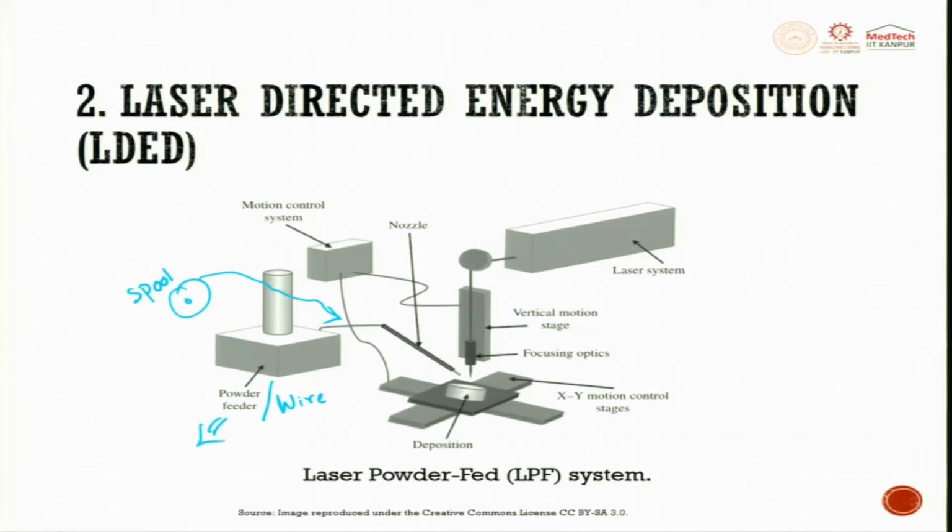So, the interesting part is you can have alloy powder or you can have a homogeneous powder, and again in homogeneous you can have varying powder size. Depending upon your requirement, whatever you want, you can try to do that. These are all the benefits which metal additive manufacturing gives when the product is developed. So, you take a spool, this spool is fed through a nozzle, and when it comes here there is a laser which hits here.